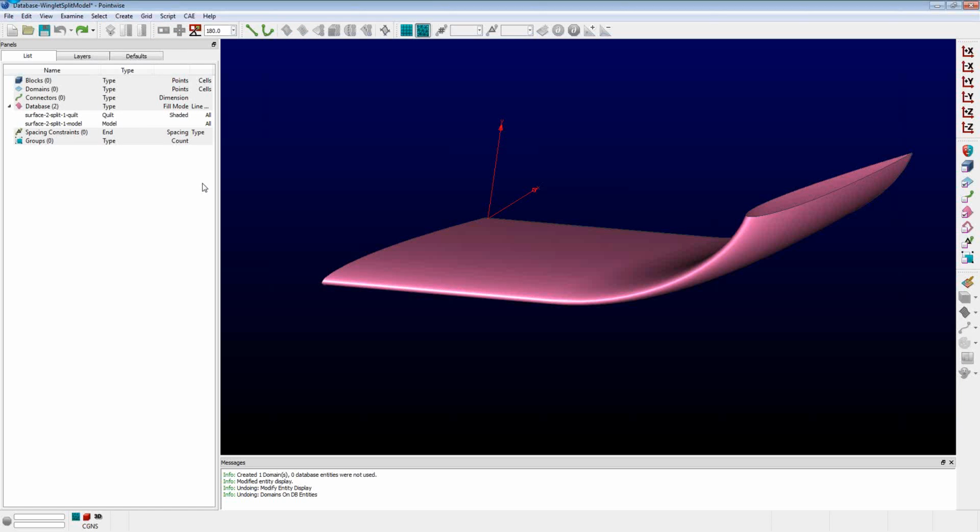Well, in fact, that tool takes on multiple roles, and I'll go into a little bit more detail about that a little bit later on. But a true split operation in Pointwise is a separation and reparameterization of the resulting surfaces. So for example, we have a single surface, we would split it into two physical surfaces, each with their own UV parameterization. Okay, that's a physical split operation.